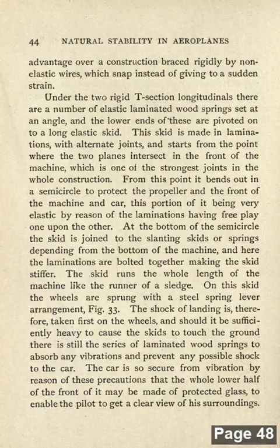Fig. 33. The shock of landing is, therefore, taken first on the wheels, and should it be sufficiently heavy to cause the skids to touch the ground, there is still the series of laminated wood springs to absorb any vibrations and prevent any possible shock to the car. The car is so secure from vibration by reason of these precautions that the whole lower half of the front of it may be made of protected glass, to enable the pilot to take a clear view of his surroundings.